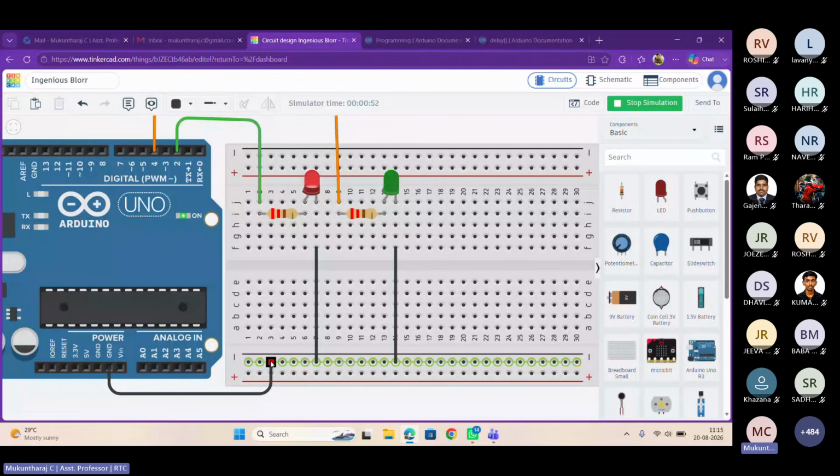If I keep my mouse there, the green dots show that all these lines are connected with the ground only. For this LED to connect with the ground, on the cathode line I have taken one wire. It must be connected somewhere over the green dots. You can connect anywhere. I can connect at this point, I can connect here too. That's not a problem at all.